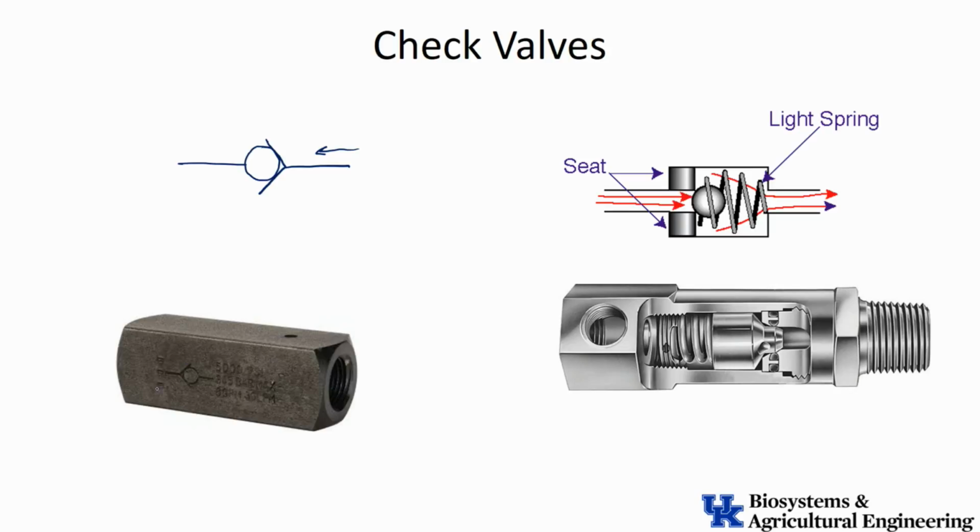And notice that this manufacturer actually shows the JIC symbol on the outside of it. And that gives you directionality too. So I can look at that symbol and I know that in this particular valve, the flow would be free flowing from left to right, but from right to left it would be blocked. And so that tells me what goes on with the check valve. So that's the simplest one, the check valve.